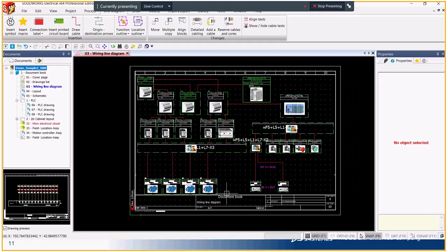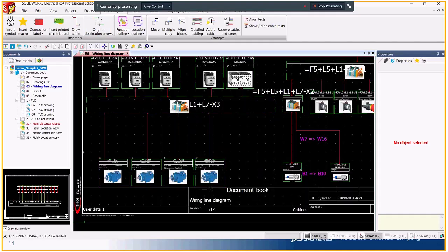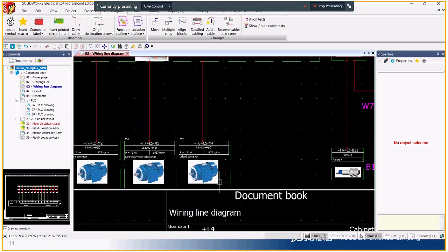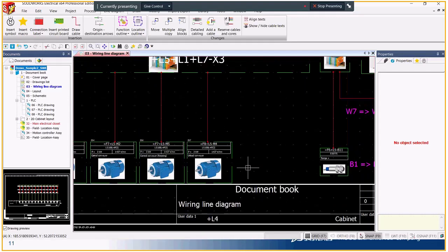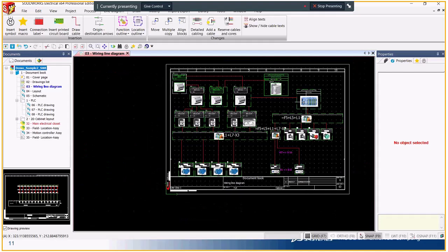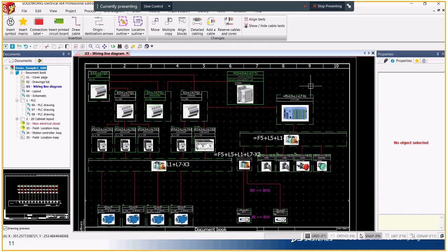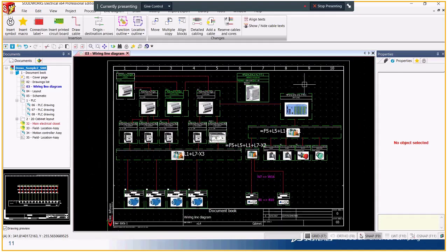We will go to the multi-line. Let me take you through the multi-line schematics. We will add a motor and the reference configuration there in the multi-line schematic, and we'll come back to the single line diagram and update and associate this. Then we'll go ahead with the PLC and terminal strip generation, and bill of material, and then we'll go to the 3D, and I will demonstrate how the collaboration between the electrical 2D and 3D can take place. Let me quickly demonstrate how it can be done.